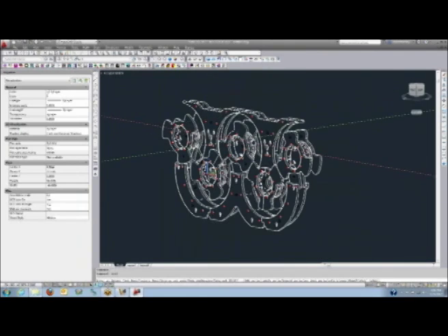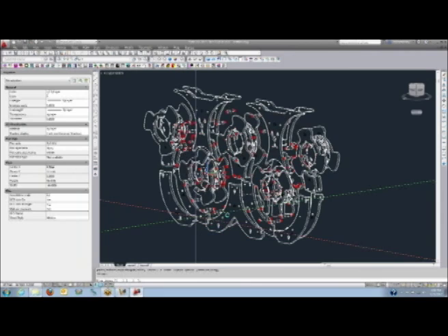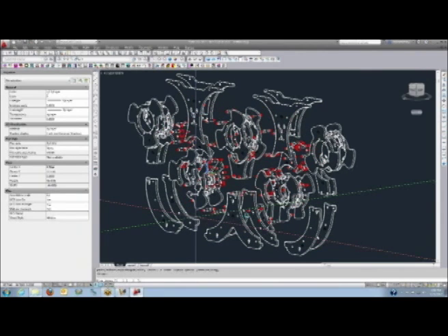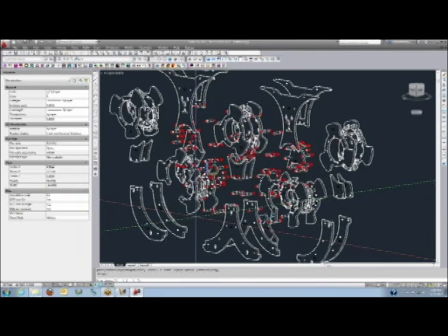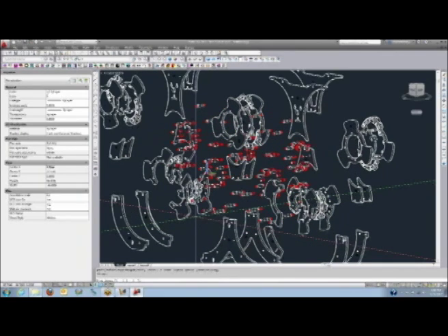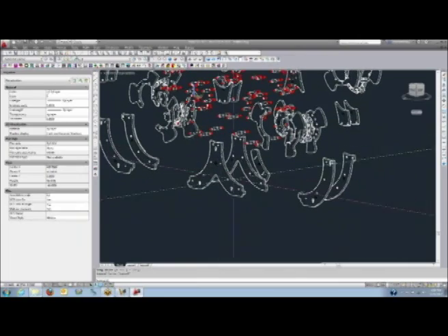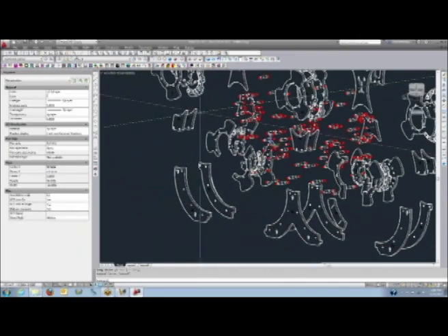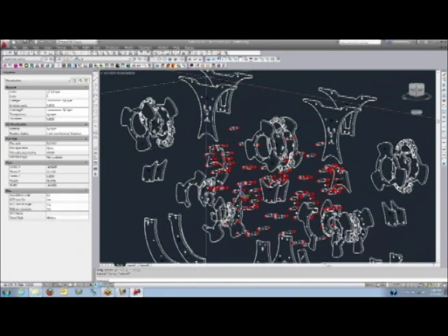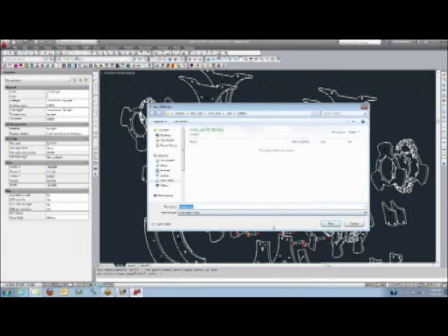So once I have a cut list like this, I have those individual part numbers. You can see the part numbers here. Another feature in the Solid-CIM program is to expand all the parts out. This is a visualization feature that lets you expand them or blow them out so that you can do an exploded view on the model. And the part numbers are listed on each part still as they're exploded out, so it helps to assemble the model as well. Those are going to be the numbers that we also generate when we make the NC code. So the main thing Solid-CIM does is it exports this information to the CSV file, to a cut list.